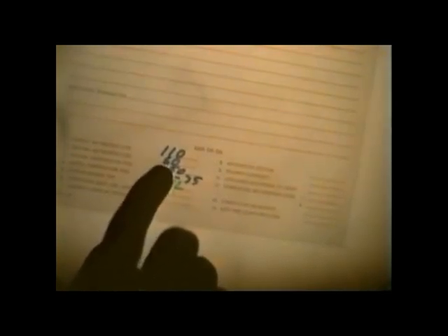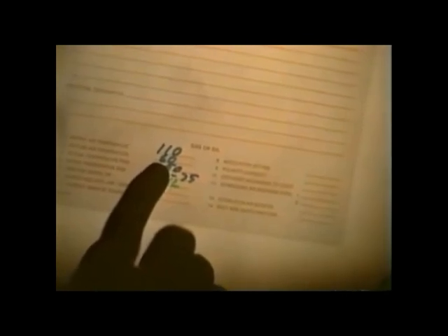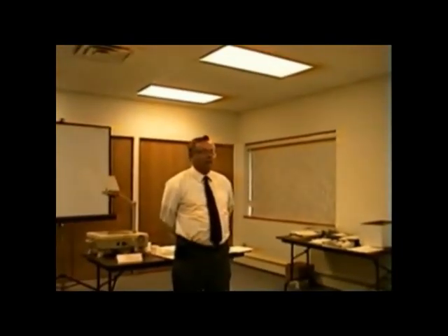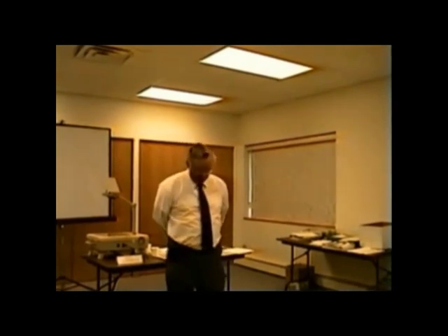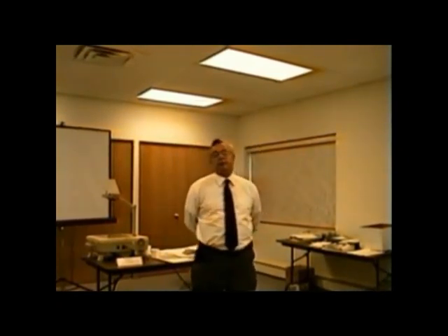So now we could actually change it, and we could end up maybe getting a temperature rise of, let's see, what would be the highest temperature rise we could get? If it's 75, and we got 60, 60 and 75 is what, 135? Yes. Be 135 degrees. So we could go to medium-low, and maybe we could bring the temperature rise up. But look at it. Let's go back. Even at the highest temperature rise, 135, and that customer was used to 160. Ladies and gentlemen, I hope you understand that we have to advise our contractor that they have to explain to the customer that it's a high-efficiency furnace. Because it's high efficiency, we give up some comfort.